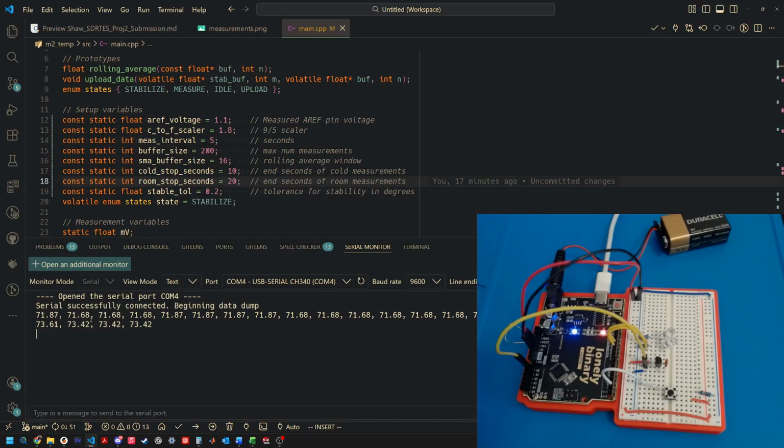As far as what I'm outputting, I was seeing some weird stuff in my experimentation. In fact, it's still here a little bit, where the calibration data is a couple of degrees lower than whatever the measurement data is. I believe that comes from powering the temperature sensor and the LEDs. Because both of those LEDs are on during that stabilization period, I think you get slightly different temperature readings. Either way, it works for the purpose of stabilization, in that those LEDs remain on the entire time, and so you're still looking for just a stable value.